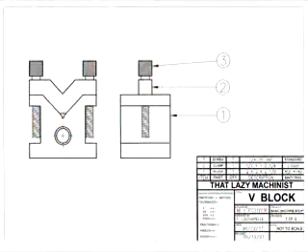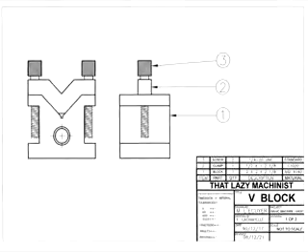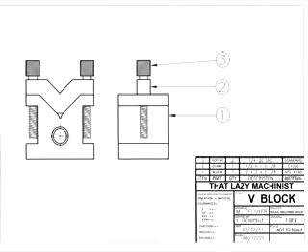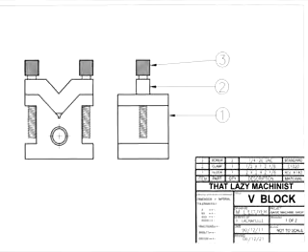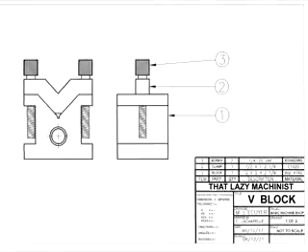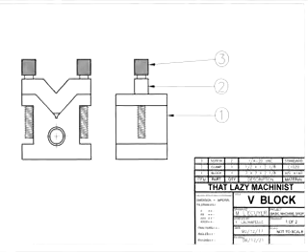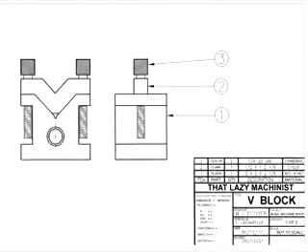Remember that I've mentioned on several occasions that to be manufacturable, a part's dimensions must be toleranced. A dimension that doesn't have a tolerance cannot be attained. Well, reference dimensions don't have tolerances, and how can that be? Well, it's simple. Reference dimensions are not used in the manufacturing of parts.